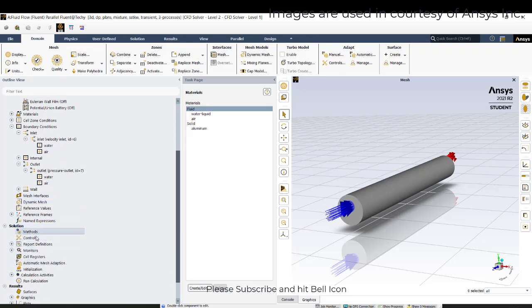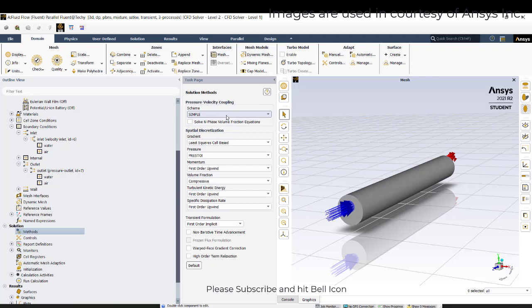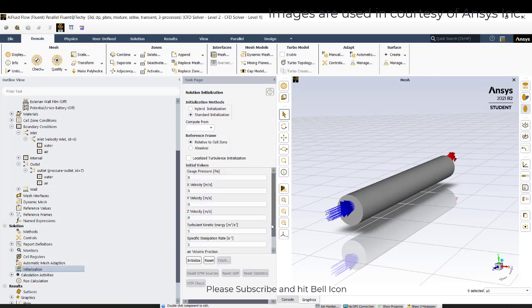Now we can go to methods, and I'll select a coupled scheme, which is much more stable and has higher order relaxation terms, so that my scheme will be much more stable. Then I'll go to initialization and initialize. Here the entire air fraction is 0.